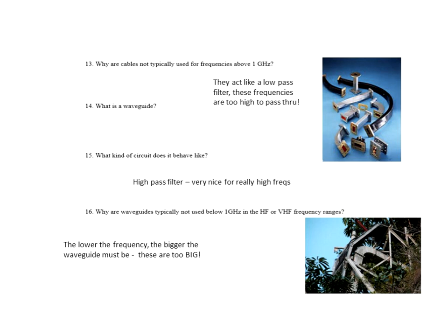So you're going to get too much attenuation. It will not let the signal pass through because cables behave like a low-pass filter. For those applications, if you're not using wireless, you might use something called a waveguide for frequencies that are up in the UHF or SHF range. Anything above VHF or UHF, you probably want to stay away from cables because they have too much attenuation or loss. Here's some pictures of waveguides here.